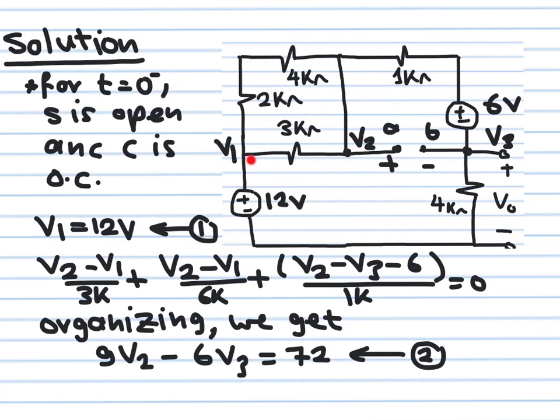Okay, so the sum of the currents flowing from each one of these nodes is equal to 0. As we agreed before in nodal analysis, you can't write KCL here. Why can't you write KCL here? Because you have a voltage source connecting this point to ground. So you have to write an alternative equation. The alternative equation here is obvious. I can't write the sum of the currents flowing out from here equal to 0, but I can say that V1 is equal to 12 volts because I took this point here as ground. So the voltage here V1 is equal to 12 volts.